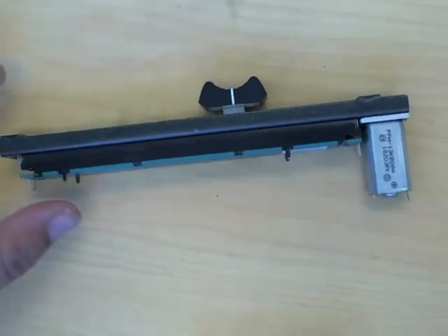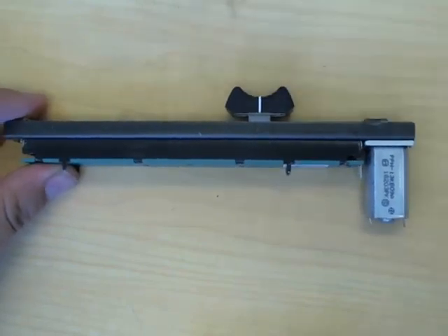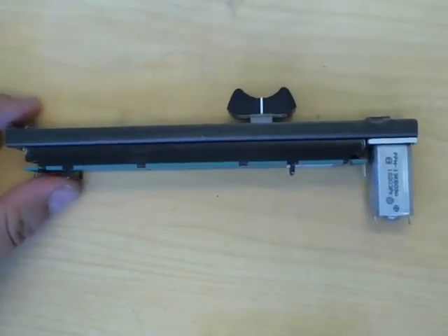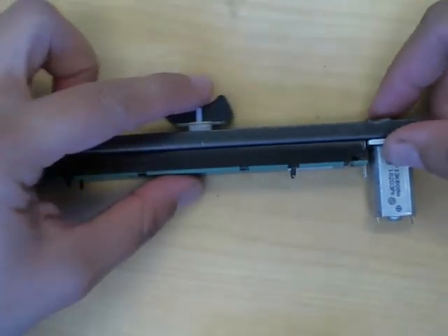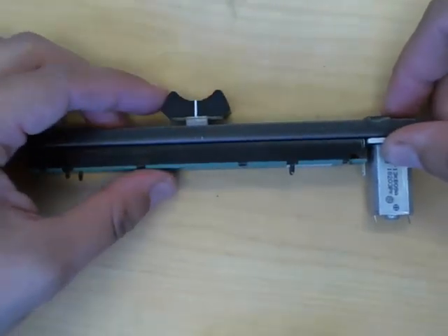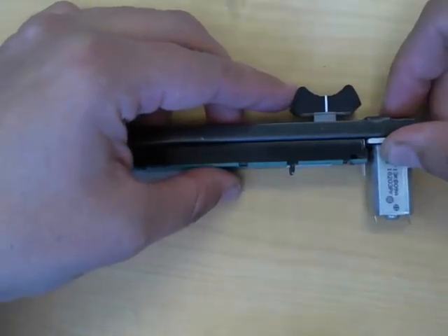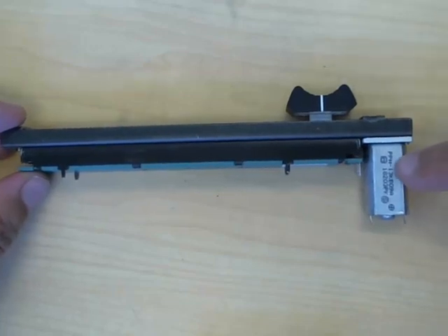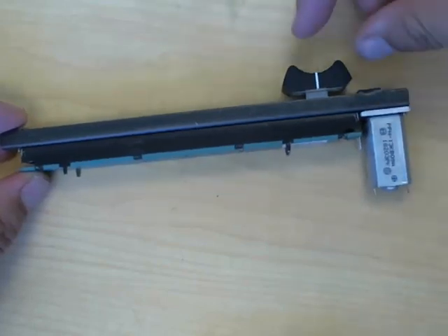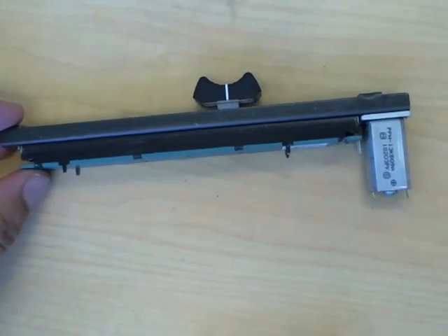The easiest way to do that would be to use something called open loop control. In open loop control, what we'll do in order to control the position of the slider is we will position the slider at a starting point, and then we will apply a voltage to this motor for a specified amount of time in order to move the slider only a certain distance.